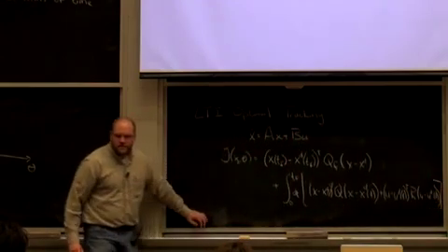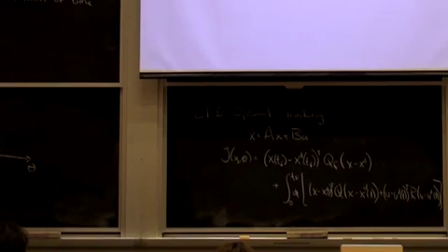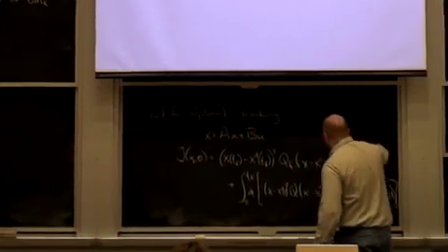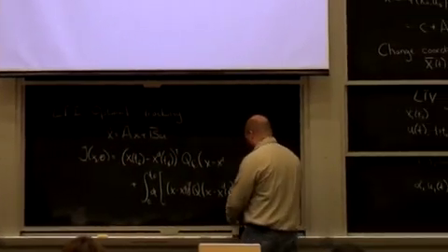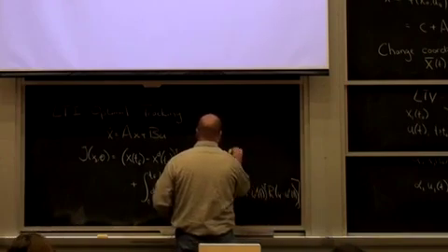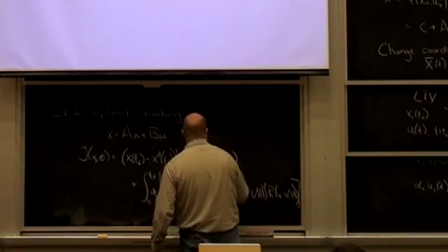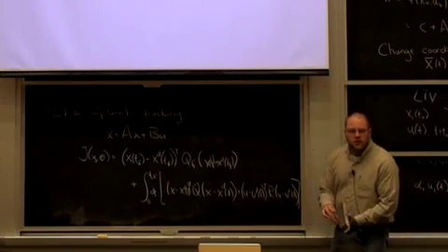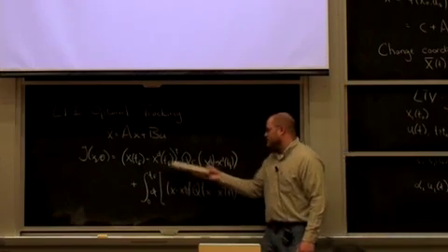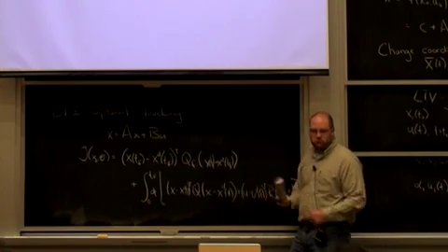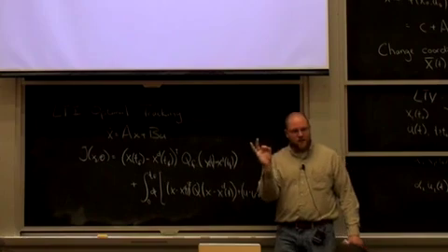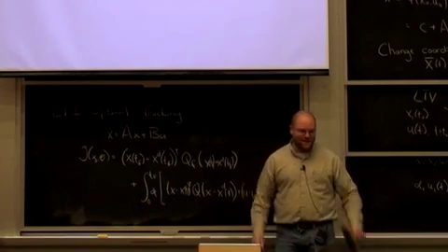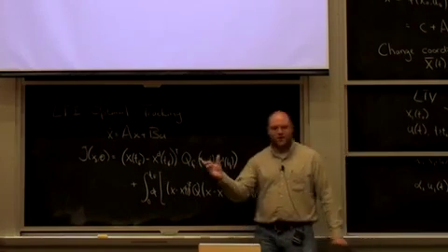Let's think about this problem for a second. Okay? So let's say I have a linear system. Now the LQR controller we did initially, a little sloppy with that, but the LQR controller I did initially always assumed that the desired place you wanted to be in life was 0. Right? If the desired place you want to be is a constant, it's 3, let's say, then you can still do your same old linear quadratic regulator, just move your coordinate system so that 3 is 0.